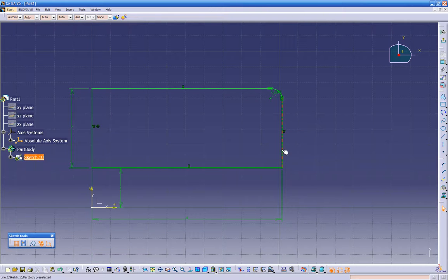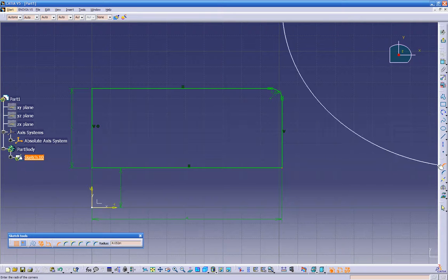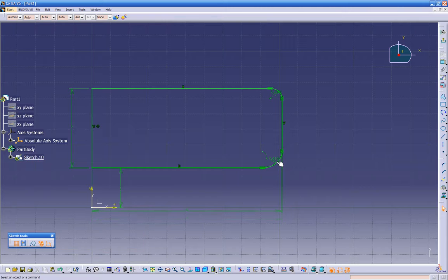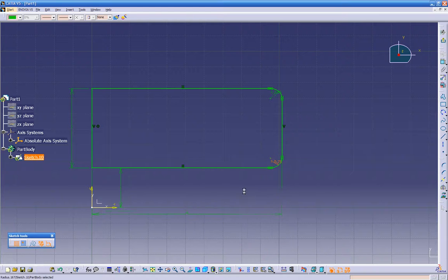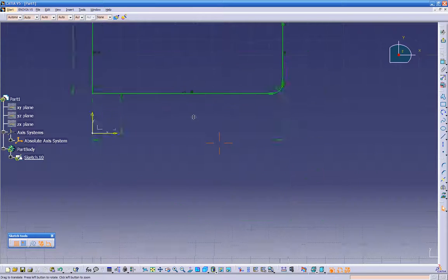Or we can, instead of pre-selecting the lines like this and going to the corner radius and giving it the dimension, just drag the mouse and highlight the point. As you see, it got brown, and click on the corner radius, and we can do the same thing. Go to the tab down here, and double click on the dimension. Call that 250 also.